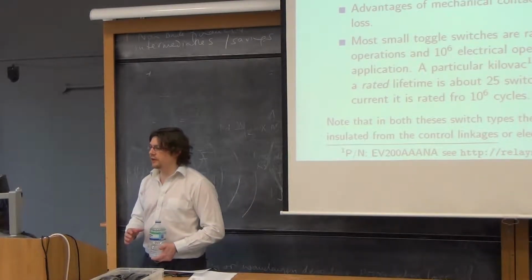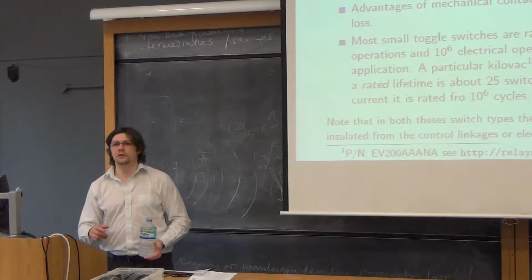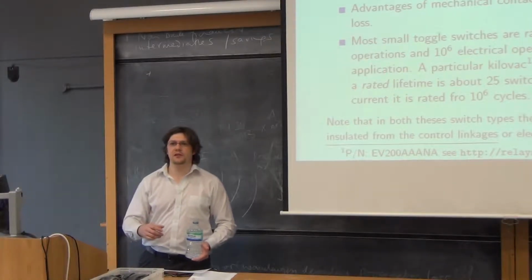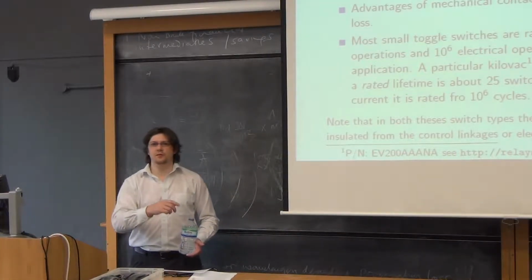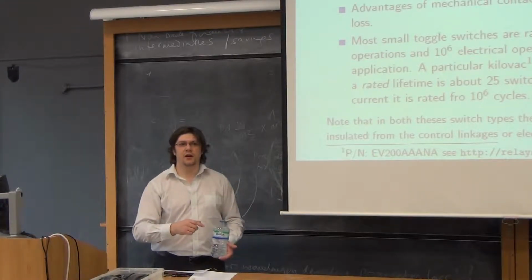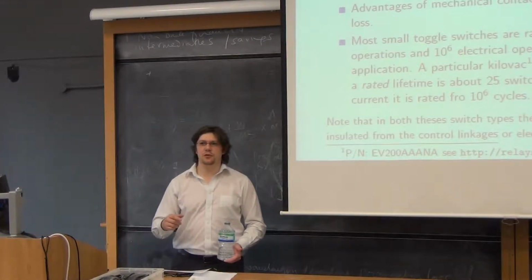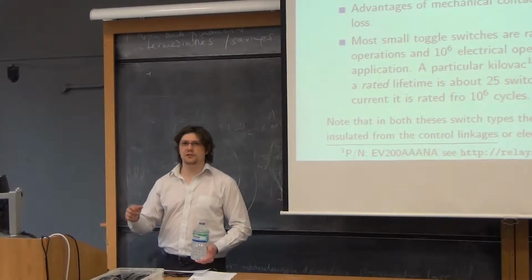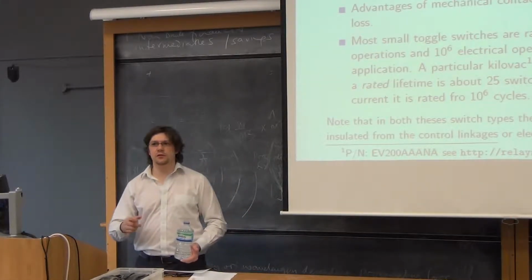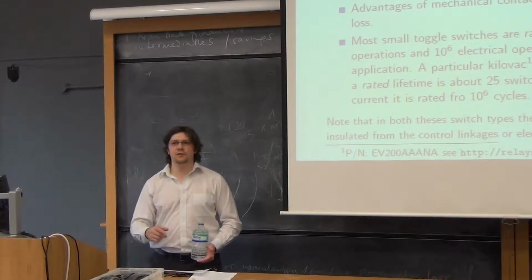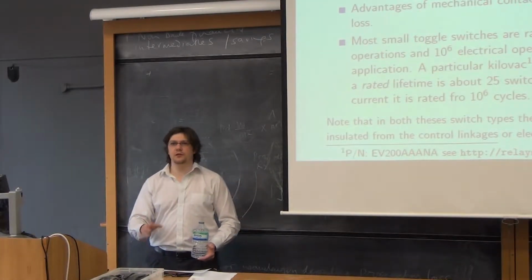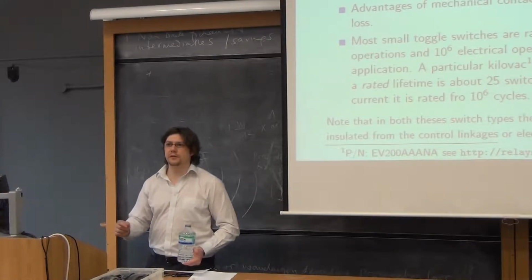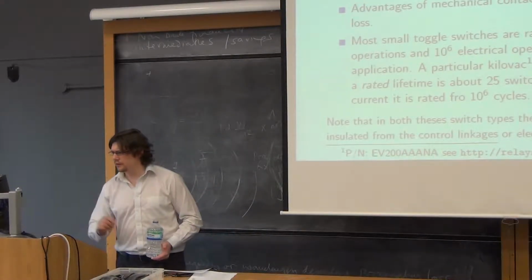That's one of the main difficulties of a transistor: you've only got 3 electrodes, but you'd like a controlling parameter, which is probably going to be a voltage, so you've got a positive and a negative, and you're switching a circuit which also has a positive and a negative. So really, you want 2 positives and 2 negatives. But with a transistor, you've only got 3 electrodes, so one of those electrodes must be shared between your driving circuit and your driven circuit. And we'll come on to that in a minute.